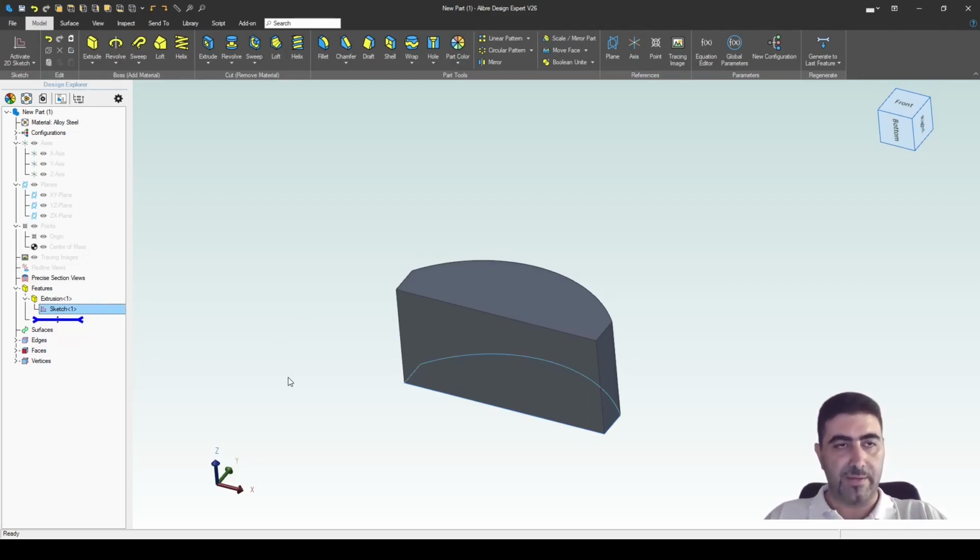Okay. Another term you might hear when discussing CAD systems is we need a sketch that is watertight. That's a good way to think about it, because you can imagine that your sketch is the outside of a vessel, and if you pour water into that vessel and it holds it, then your sketch is watertight.